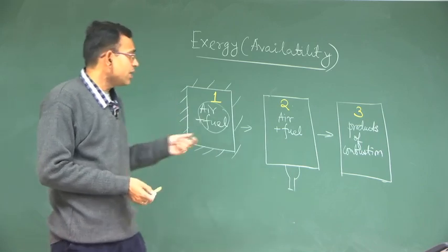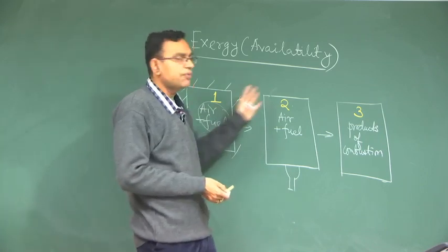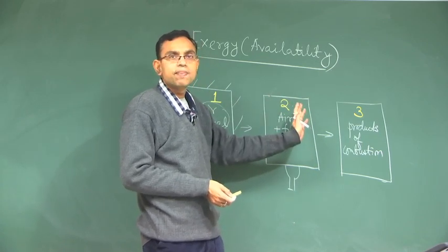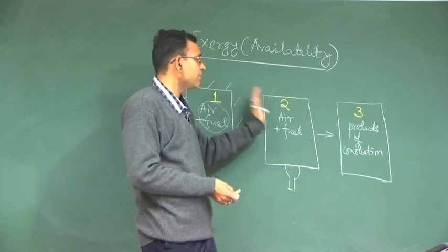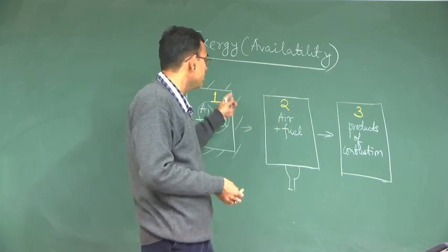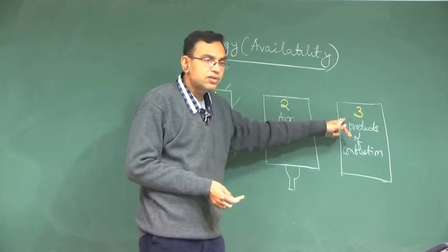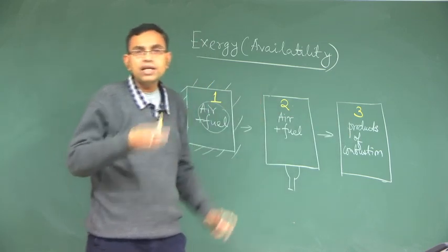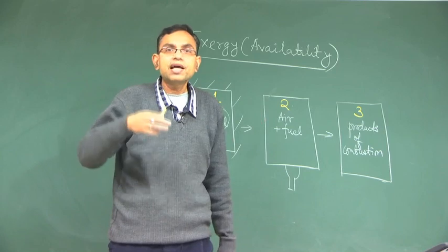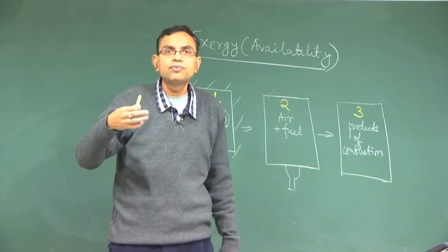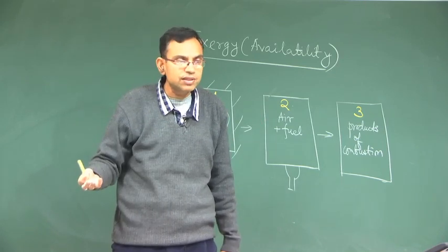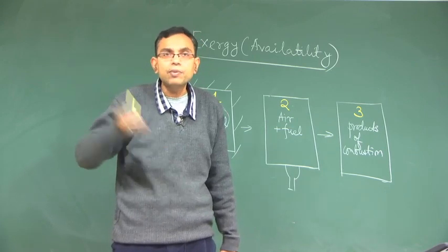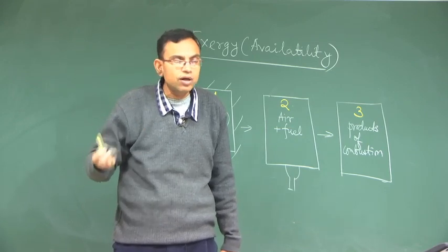So, although the quantity of energy remains conserved by taking into account heat transfer and all this, the quality of energy has degraded as you go from state 1 to state 2 to state 3. High quality of energy means high capability of extracting work out of the system. Low quality of energy means low capability of extracting work out of the system.